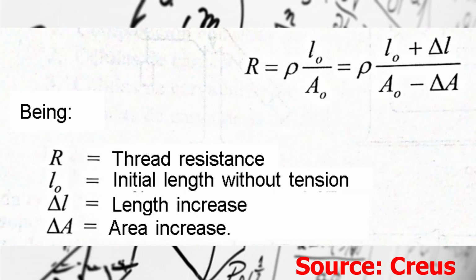The tension or compression to which the weight subjects the load cell makes the length of the metallic wire vary and therefore modifies its electrical resistance. This resistance is calculated in this way. As the volume of the thread is constant, before and after it is put under tension, it is calculated like this, and the resistance change as the second formula.